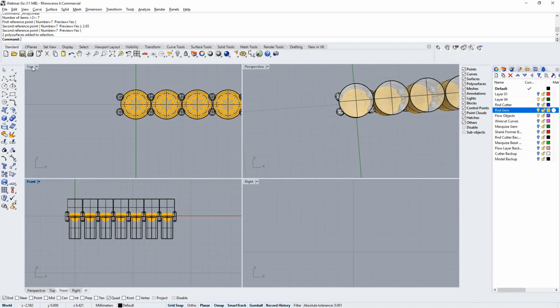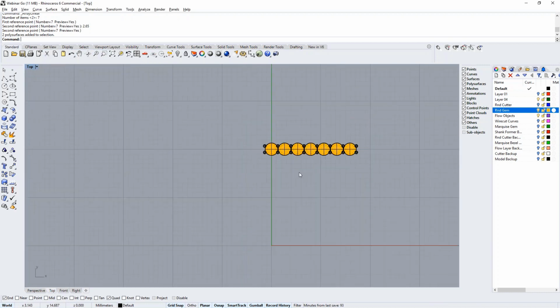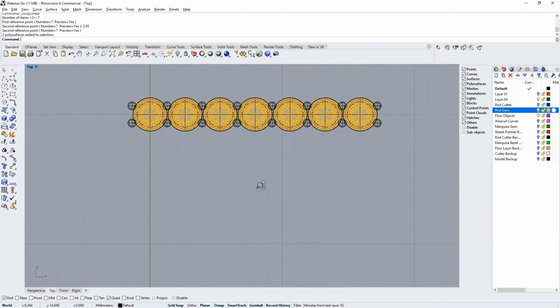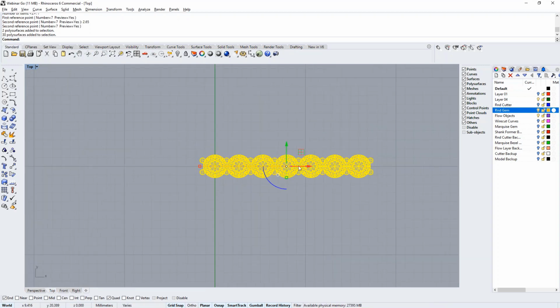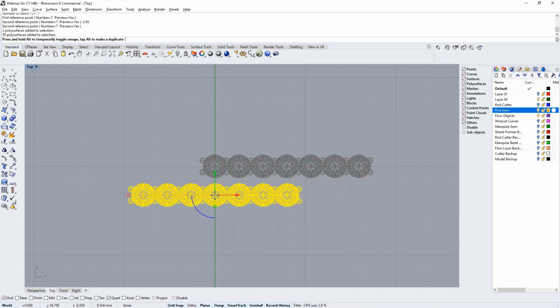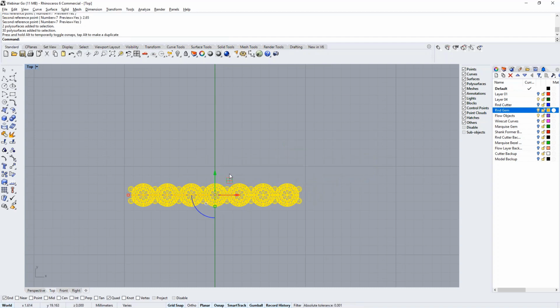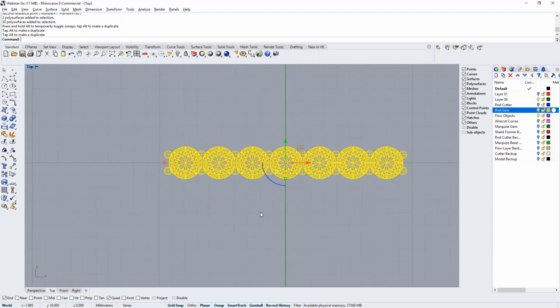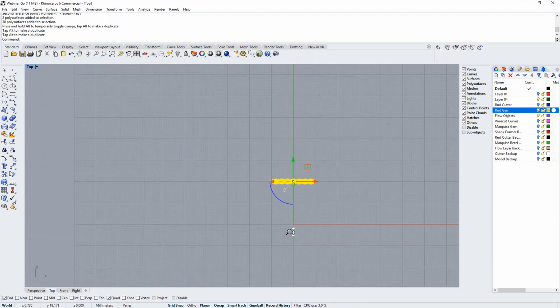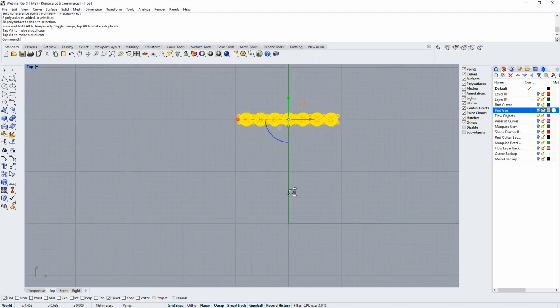Okay, so now we're going to make a line here that will be our flow line. Or actually, let's get all this stuff. For some reason, I like to work with stuff centered. So let's take all of this stuff and put it right on the y-axis, and we'll move it up here so that it's pretty well centered on our view screen here, and that'll be centered with the 0, 0.